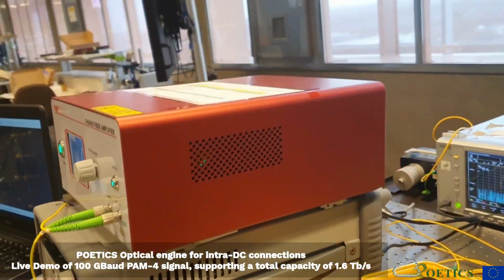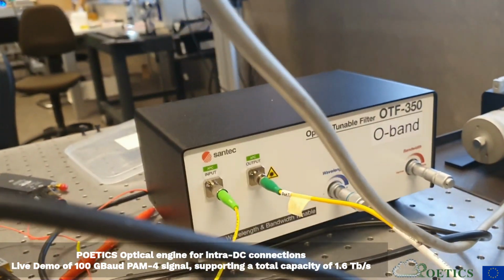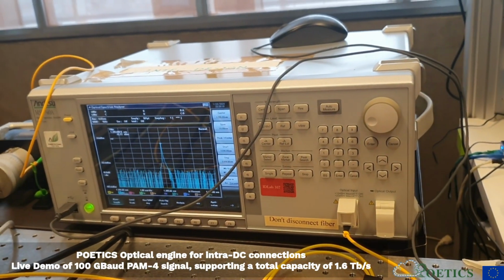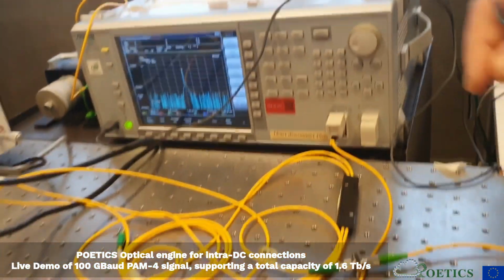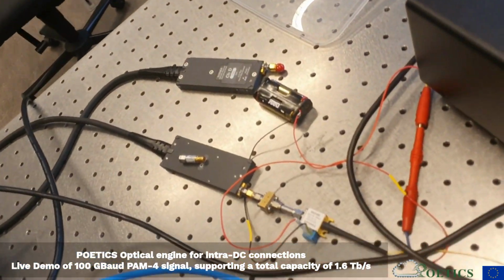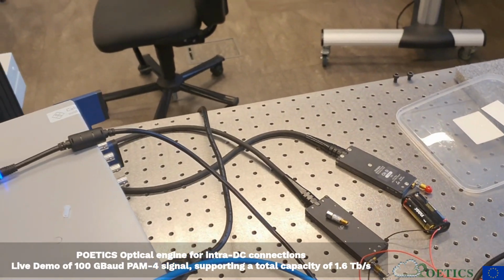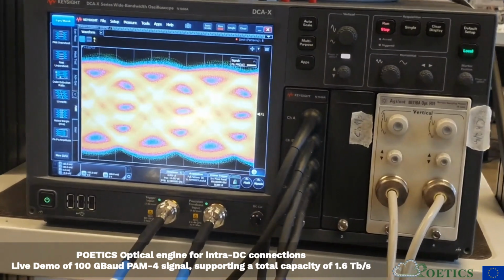And then we use an optical filter, a passband optical filter, in order to filter out some of the noise that is generated from the amplification stages. We use a tap monitor to be able to monitor our optical signal in real time using this optical spectrum analyzer. And we use a photodiode to detect the optical signal and generate the electrical signal. From the photodiode, the electrical signal gets routed to the sampling oscilloscope, which you can see right now,